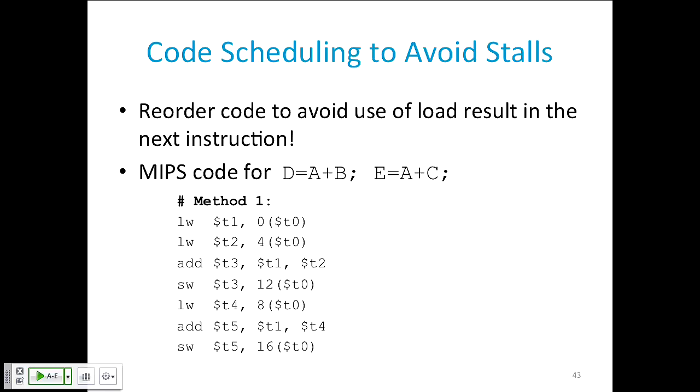This calculates D equals A plus B, E equals A plus C. There's a little bit of code that does this in MIPS. So load, this is doing this expression: load, add, store. And then for here, load C, add, and store.